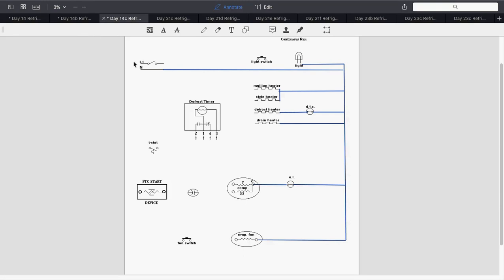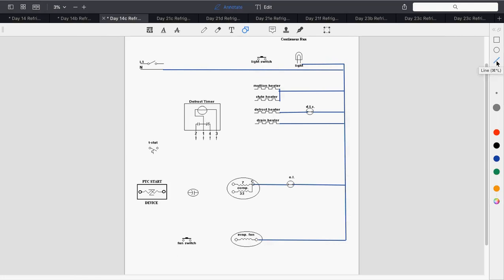That's exactly right. Or the newer ones have the condenser coil buried under the sides, right under the metal of the outside case. So if you feel the side of it when it's running, it's warm. That's where the condenser coil is, and of course we won't have a condenser fan motor.